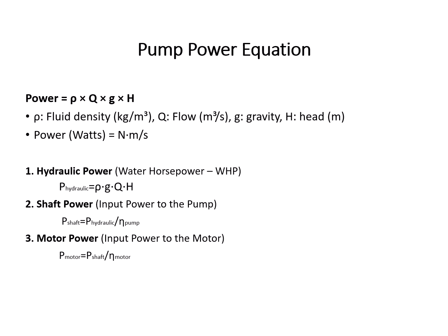Okay, so this is the power. Actually, we have 3 powers that we need to consider when we are applying pumps. Hydraulic power, which is water horsepower, and this is the ideal power required to lift or move the fluid, ignoring losses.